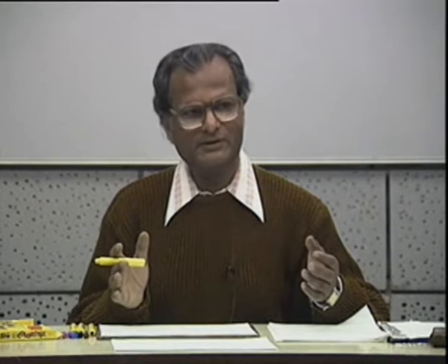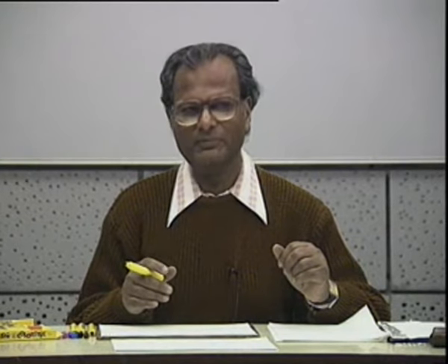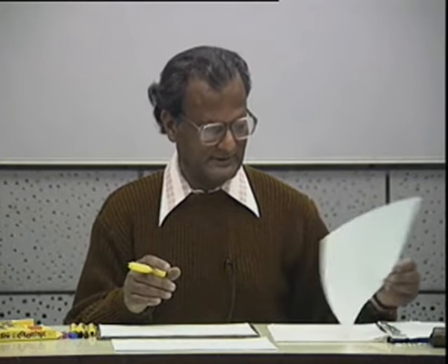Given an amplifier, a common emitter amplifier, it has a certain bandwidth. Now we want to increase the gain, and we also want to increase the bandwidth. So what do we do? How do we wide band an amplifier? And we shall see that we will encounter more than 2 transistors, and that the methods of open circuit and short circuit time constants are very, very handy methods for calculation of the performance of such amplifiers.